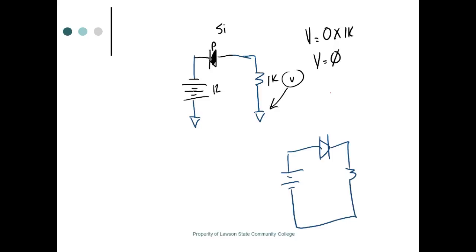So in AC, where do you need to put your black lead? It doesn't make any difference. AC has no polarity. You get people talking about that too. You don't have to put that black lead on the neutral in AC. In DC, you don't either. But in DC, if you put it on there backwards, your voltage measurement polarities are going to be backwards. Y'all understand that? But digital meters don't care.